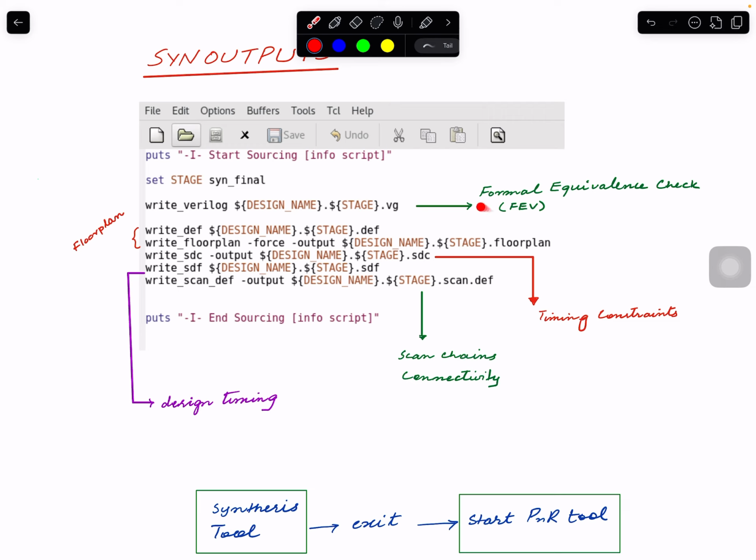So this is a separate flow that is checked after some of the major stages. People check it after synthesis, then later on after routing, and maybe once after the very final design. Okay, makes sense? So for that we need the netlist. Sometimes the DFT team, which is a separate team, is doing their gate level simulations, and they need the scan stitching information inside. So for them, they need a netlist, and it can be used there too.